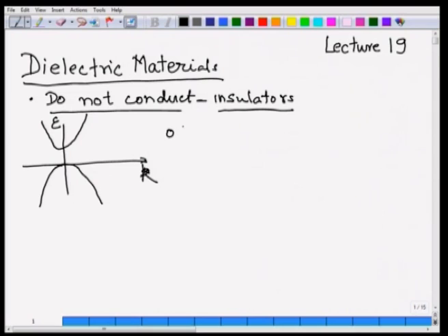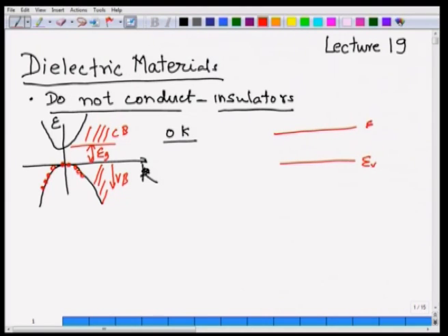If we looked at a temperature of 0 K, this place was full of electrons. There were electrons everywhere. The valence band was full of electrons, whereas the conduction band, which is this higher band up here, was empty. This was the conduction band, and this is the valence band. This was all valence band, and this was the band gap Eg. On this side we have Ev and Ec, and a band gap Eg. At 0 K, this semiconductor was also an insulator.